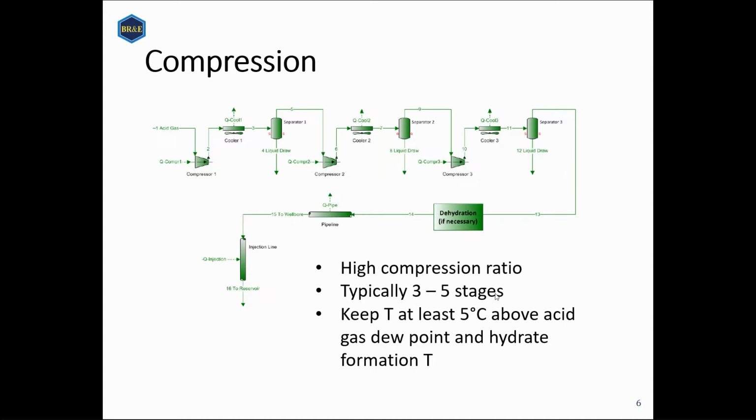So we can actually optimize this system to try to get the most water dropout that we can. And we'll be looking at that a little bit later. The lowest temperature that you're going to be seeing is probably going to be around this wellbore. So when we do look at hydrates, that's where we're going to want to focus.